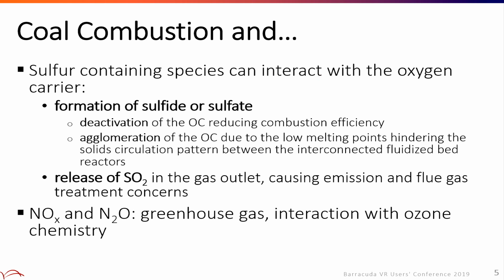Coal, as you know, is a very heterogeneous material, and the coal reaction can include various homogeneous and heterogeneous reactions, including devolatilization, and those volatile species can further react homogeneously and heterogeneously. The char oxidation is also there, and char gasification.